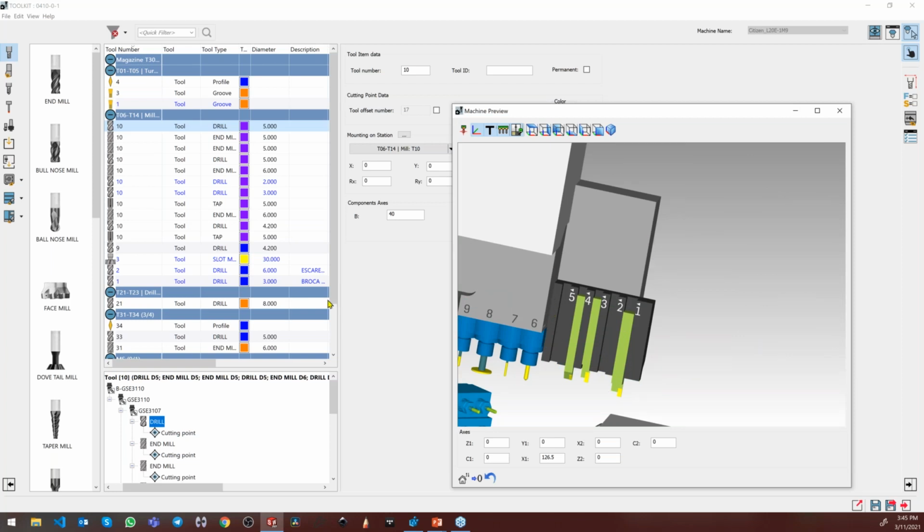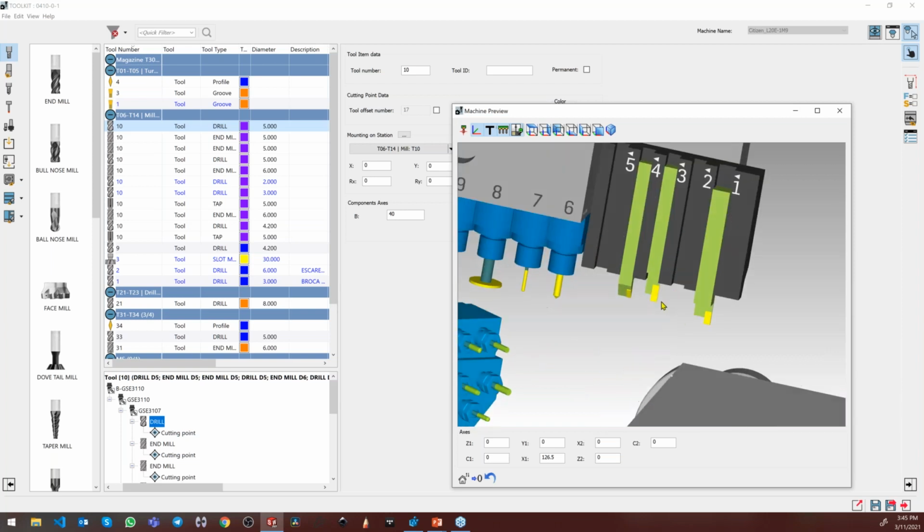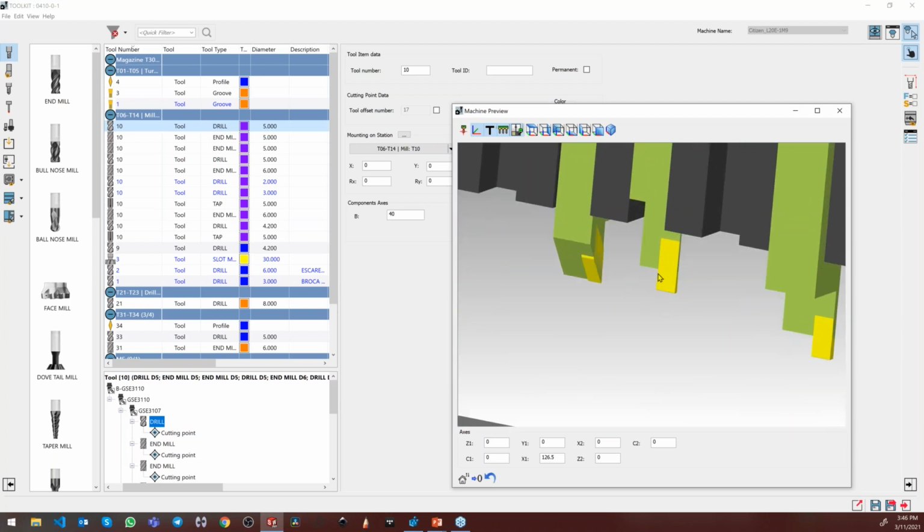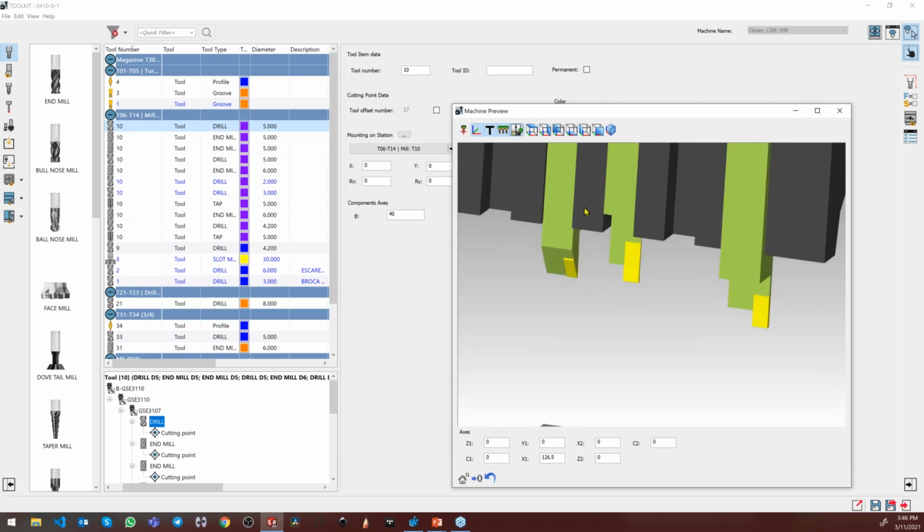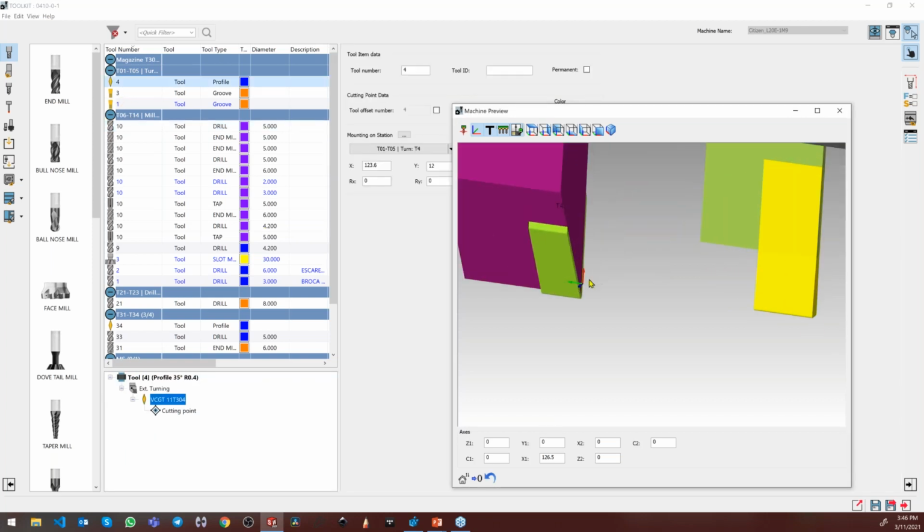I also want to show something small on this machine regarding the measurement of the turning tools. If you're familiar with this type, you know the tool, for Citizen for example, is this kind of tool. It should stick out 20 millimeters from the holder. It's not a precise 20 millimeters, but it's like a reference point. It means if you're out of the holder 20 millimeters, it's a zero. So how do you manage it in SolidCAM today? Go to this tool, and you see here's my reference point, but I am not relative to zero. And how do I know what's the distance from here to here?